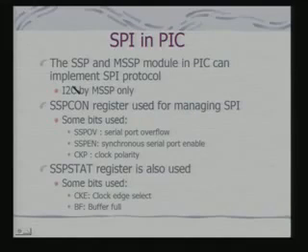The 2 basic registers, other than the data registers, which are involved in PIC for managing your SPI are SSP con, the SSP control register, and SSP stat, the SSP status register. Some of the bits used: one is SSP overflow.